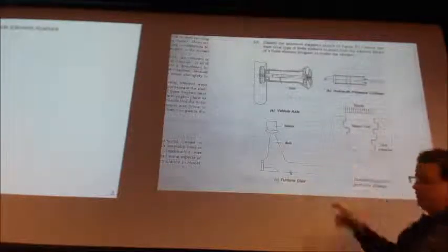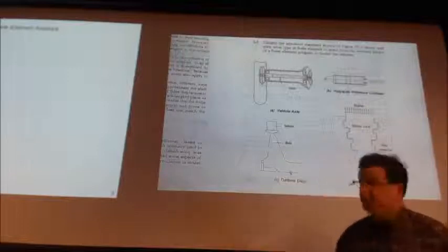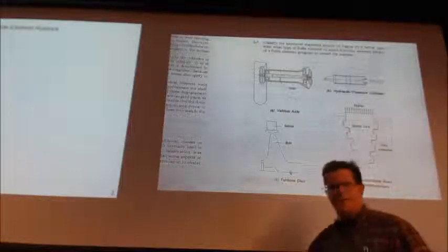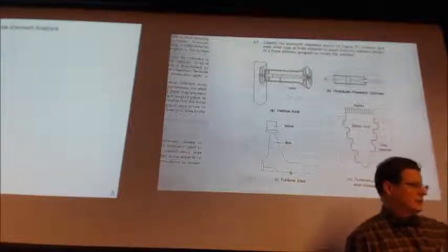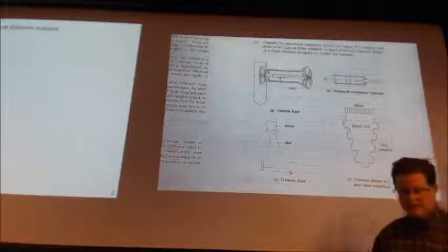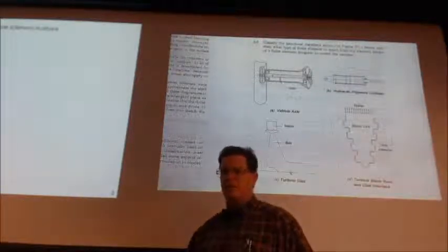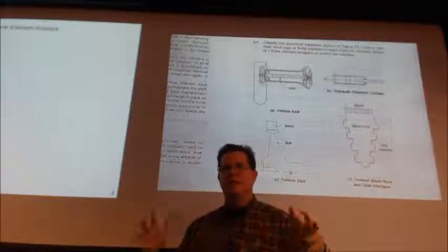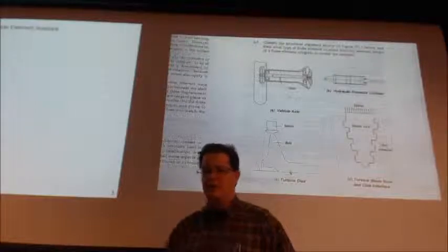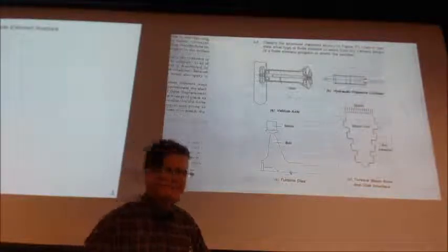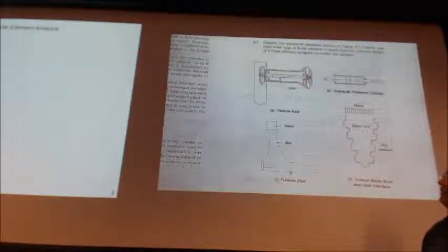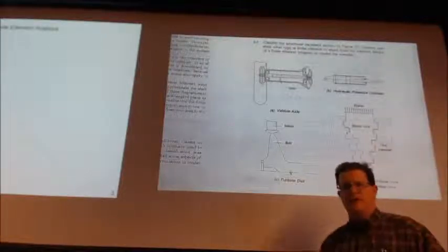But if we are going to apply that to these objects, so if we were going to do the axle, what do you think we would do for the axle of this? I don't know what it is, some vehicle obviously. If we were going to pick a truss or a beam or a solid or a plate or a shell, what do you think would be the structure that we would use to model that simplistically as opposed to 3D? Torsion bar and shaft. Torsion bar. So, yep, we're going to deal, well, you say shaft, torsion bar and shaft. Okay, what else though? Think about the loads that you have on it.